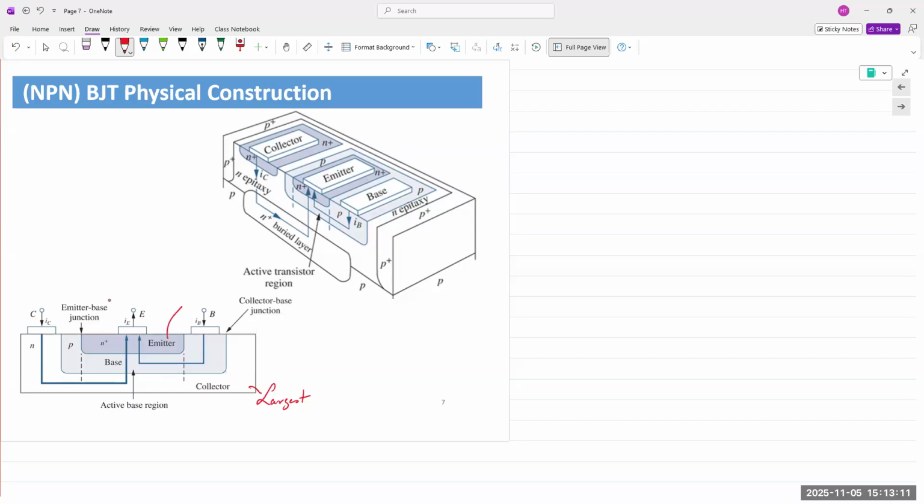Okay, I want to point out, when we actually fabricate these, we start either with a P or an N-type material. So in this case, what kind of transistor are we trying to show? It says right there in the name. It's an NPN. So the collector is from an N-type material. Now, if it's an N-type material, it is not very heavily doped. It's somewhere between the emitter and the base. As I pointed out in one of the previous slides, the collector is the largest in terms of physical dimensions, but in terms of doping, it is somewhere between the emitter and the base, right?